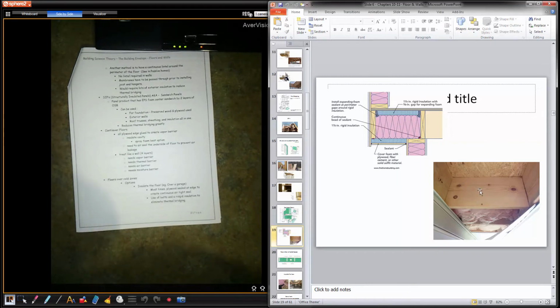That's showing typical. So that's like a soffit here. So a lot of houses built 20 years ago or so, they have the cantilever on their floor, they put fiberglass bats into it, put soffit over it, and that's it. So there's not a lot of thought put into building science. So what's stopping the air from getting here? That's like going outside with a sweatshirt on a windy day. Are you going to be warm? No, that's only the thermal. It's missing the air. You need the windbreak.